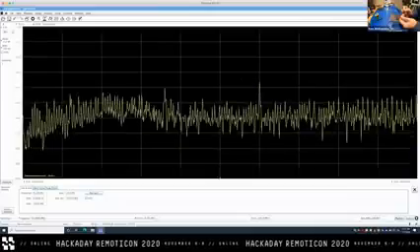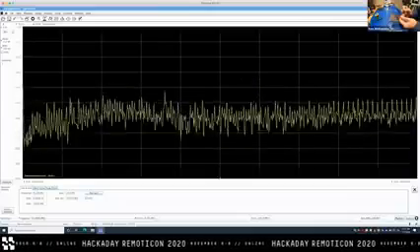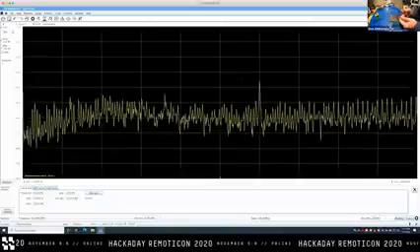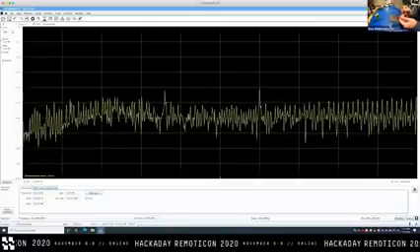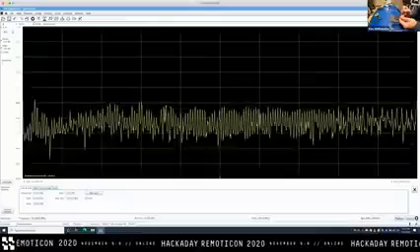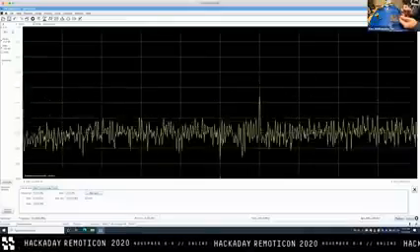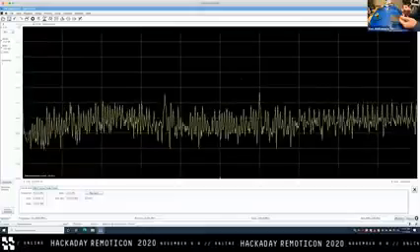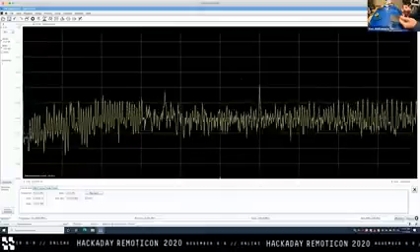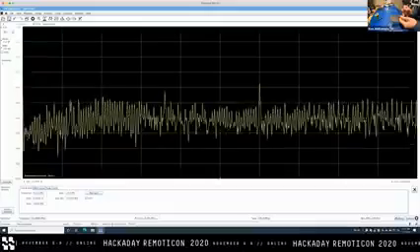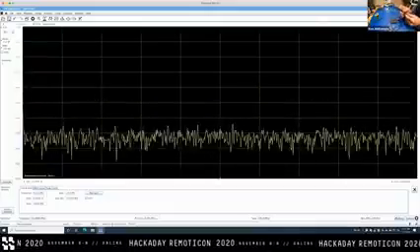And then if we come down here, we start to see a couple of other individual peaks. I see them now because I saw them earlier, but they are a little bit buried in the rest of the switching noise. So, okay, we've got some 60 megahertz somewhere over here to look into. We've got a little bit of peakiness down here. It looks like, what, 35, 36 megahertz, something like that. So let's go in for a slightly closer look.